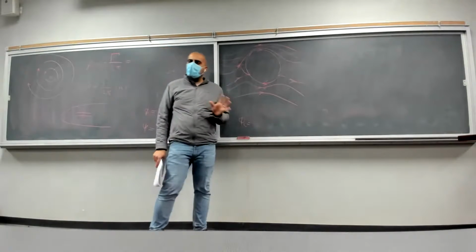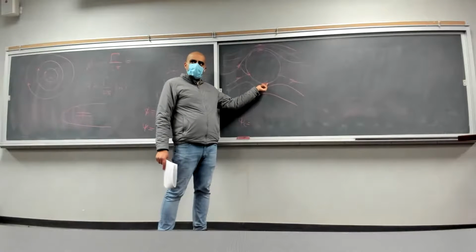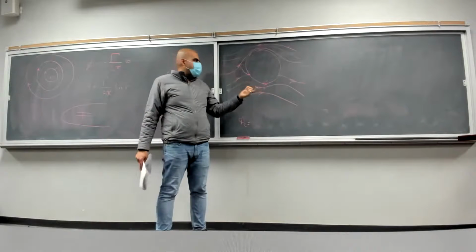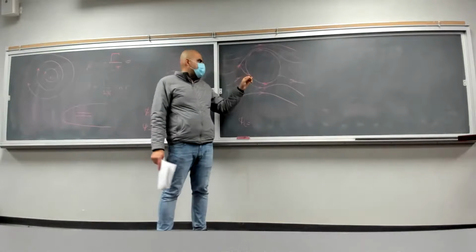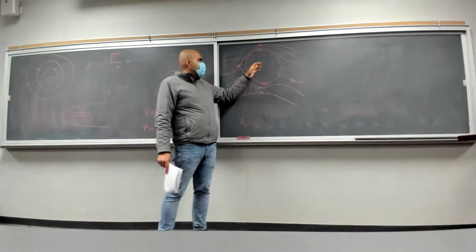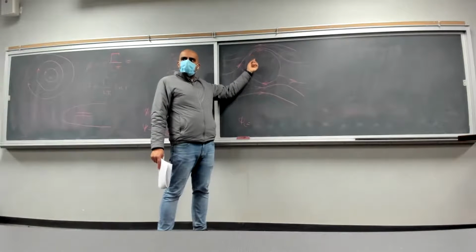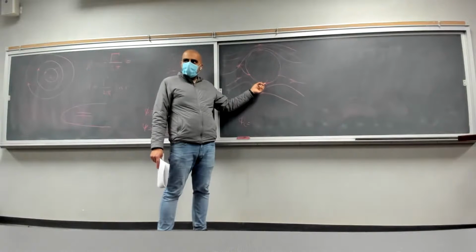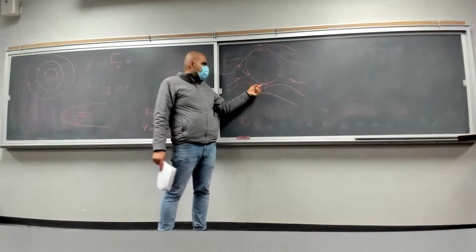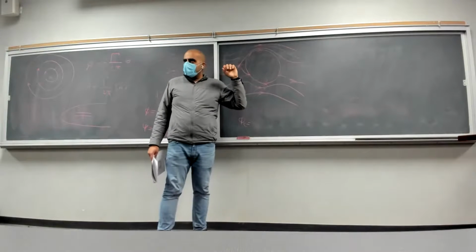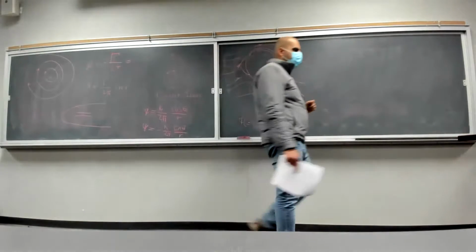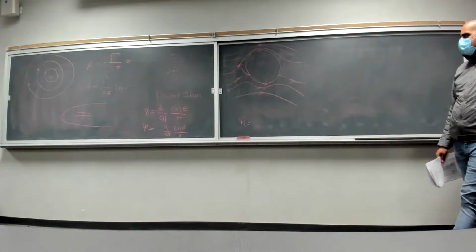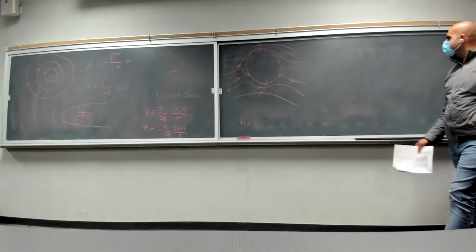It is not that hard to understand. You have lower velocity here, higher velocity here, right? And they are moving in the opposite direction. There is a situation in which you can get 0 velocity on the surface because you are moving from a high velocity to a low velocity, right? The magnitude of velocity is going to be lower on this surface, which means that 0 velocity is going to be closer to this surface. We are going to talk about this type of flow in more detail because this is the first type of lifting flow we are going to analyze essentially.